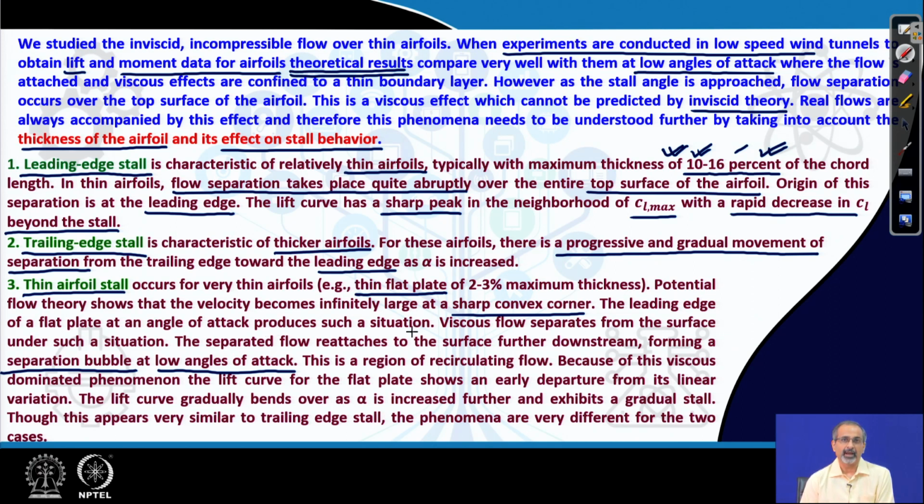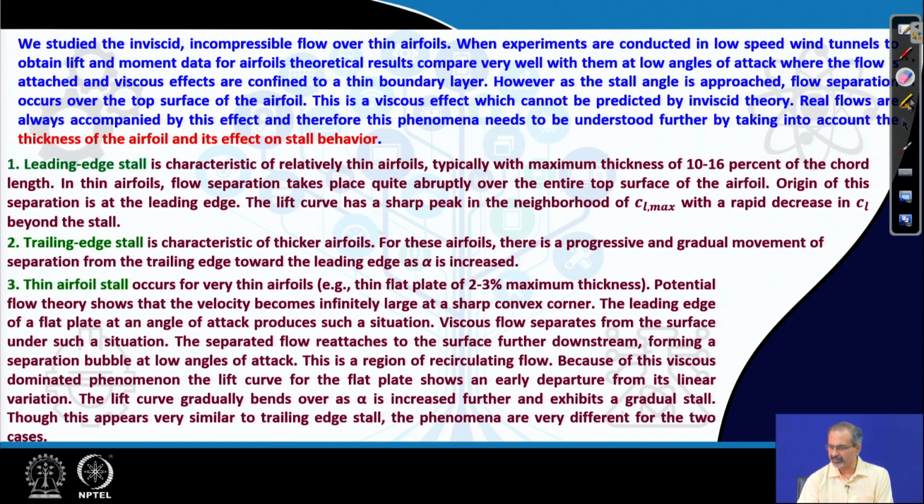and the lift curve gradually bends over as alpha is increased, but it is at a much lower level of CL max in comparison with the trailing edge stall situation that we were talking about in thicker airfoils. So, let us look at some more features of these airfoils in the next few slides.